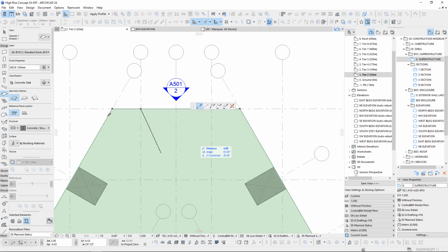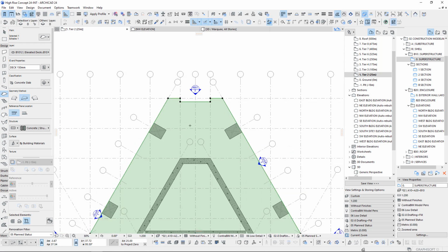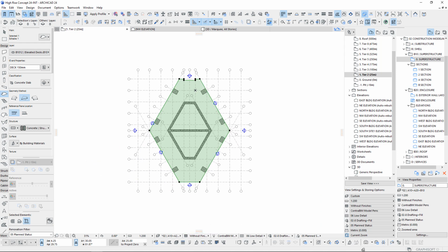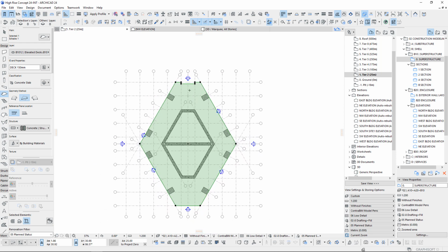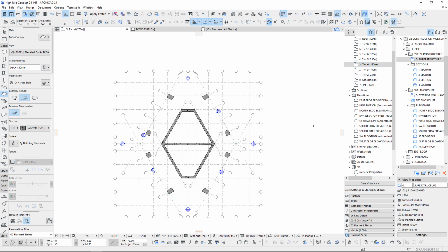So I actually believe that there's maybe a little bit of a carving out going on up on this side. So let's add in just a little bit of a notch. We'll just take this back in the Y direction, -1 foot. And I believe that we have a bit of a notch out here where there's, I think, some elevator shafts or something going on the front there. So let's take this. We'll just simply copy and paste. So now we'll have some nice references here on each of our different tiers.